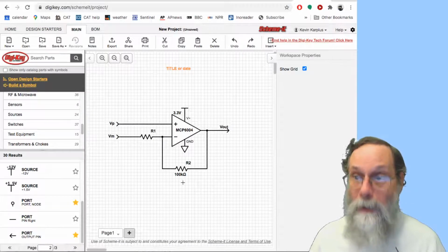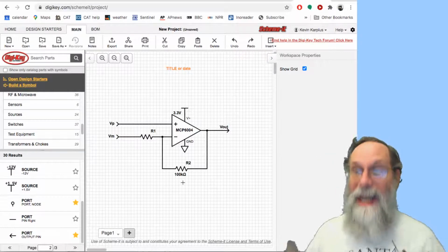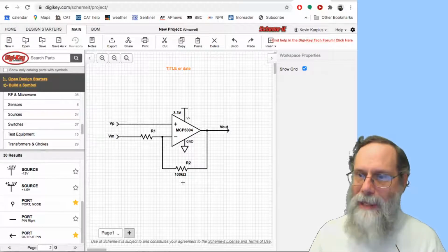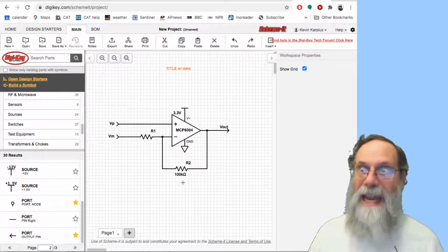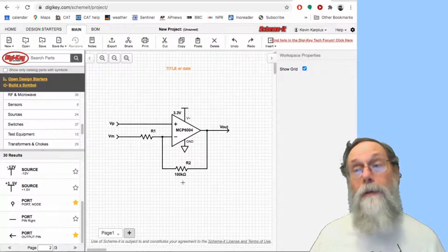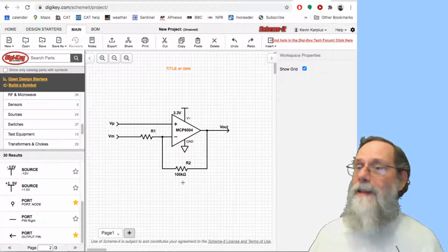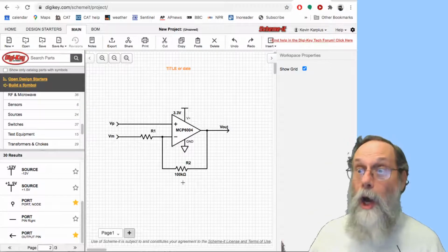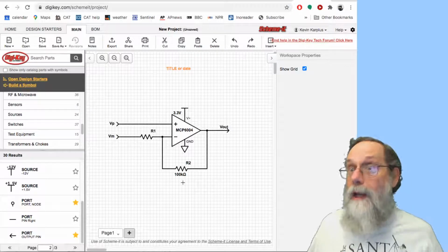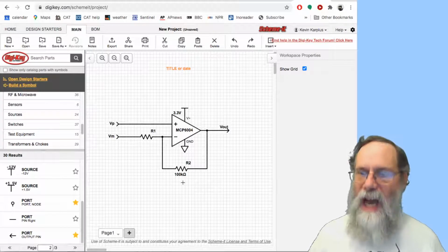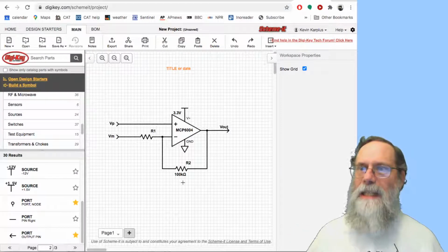I can't help you debug if you make things up in your head and don't put it down on the paper. You have to have your schematic being the thing you're trying to build. If you change what you're trying to build, change the schematic. I have to yell at you now for that to avoid yelling at you in lab, because it is such a common problem for people to think that I can read their minds, that I know what they're trying to design, and that I know their design better than they do. Show me the schematic. If it's not on the schematic, it isn't designed.